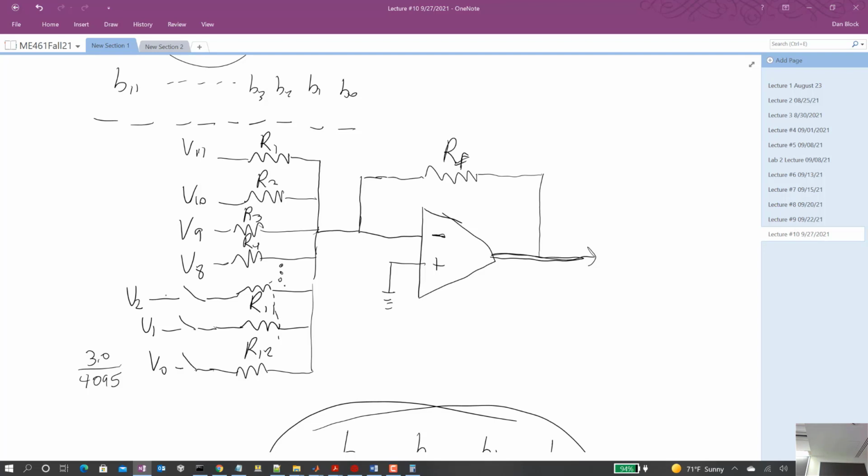Good. All right, so that's this idea of a DAC. And we'll be using it this week in lab. You'll be writing values to the DAC unit. Actually, let's see. Yeah, I think we give you the function, but either way, you'll see how it's done. You'll take the value that you want to output, say 2.1 volts, and convert that to the linear representation between 0 and 4095 that scales to 2.1 volts. Okay, so you'll be driving that to the DAC, and then the DAC will output that voltage.